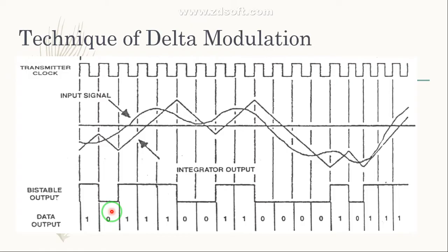Now the integrator ramps downward. See, it is going to move downward as a plus 4 volt signal from the unipolar to bipolar converter appears at the input. And again, this ramp signal tries to catch your analog input signal. So you can observe it over several clock pulses.